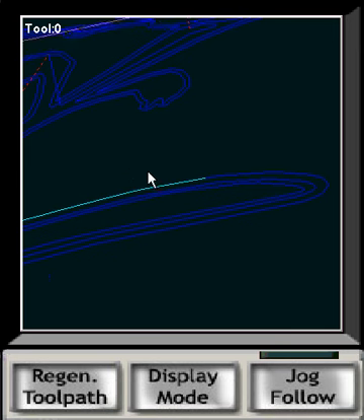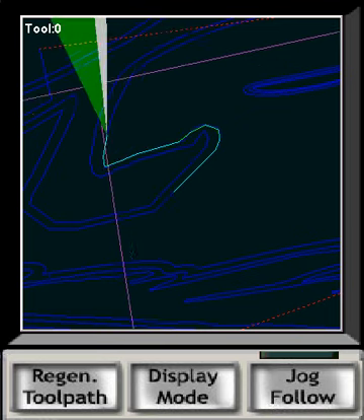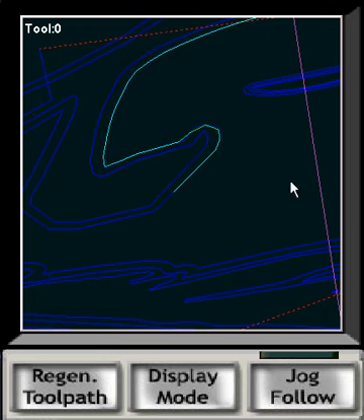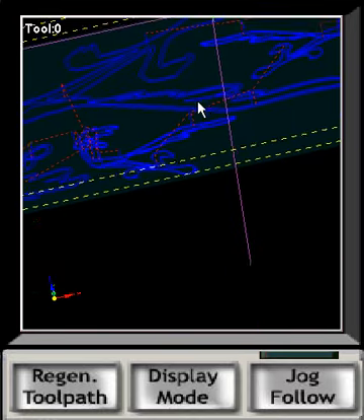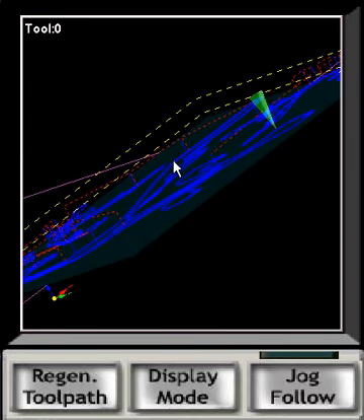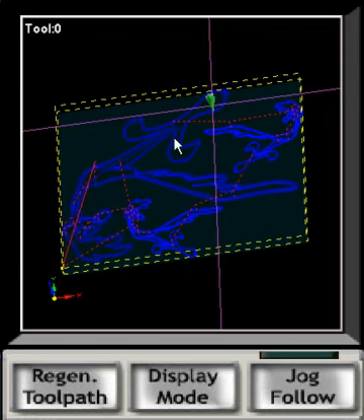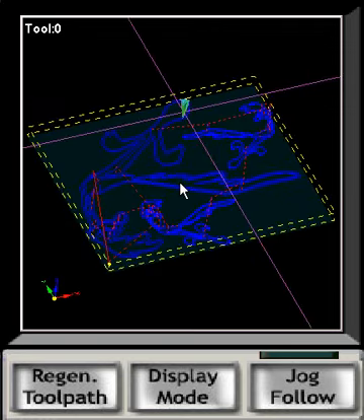Now you can't zoom or pan when the program is cutting because we don't want to interrupt the pulse stream. But you can feed hold, and at feed hold you could zoom out in the normal way. You can pan also, and it doesn't matter what angle you're at, the pan works perfectly to get you centered. So double-clicking takes you to your top-down. Double-clicking again takes you to an automatic ISO view that you'll always go to, so it's quick to just click back and forth.